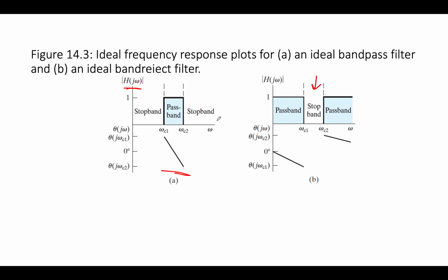Okay, so basically your axis is the frequency axis. It's important to point out that this has units of radians per second. Typically specifications are given in hertz. So if you're going back and forth between designing filters and looking at specifications, you're going to have to be sure that before you work on your filter design in the Laplace domain that you are working in radians per second. So that's just a heads up.